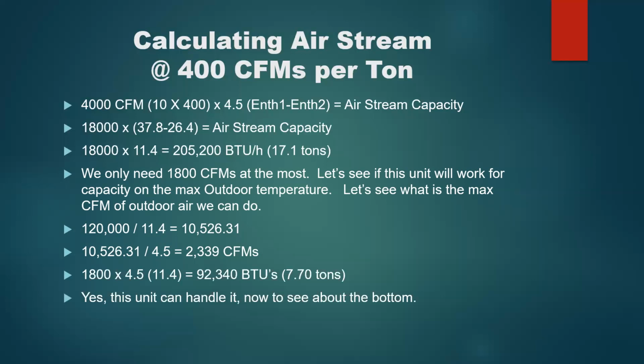So what do we have? We have 1,800 CFMs times 4.5 times the 11.4, which gives us 92,340, or just under 7.7 tons. Yes, this unit can handle it.